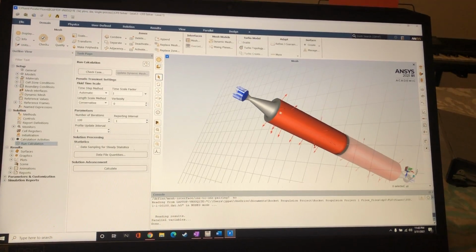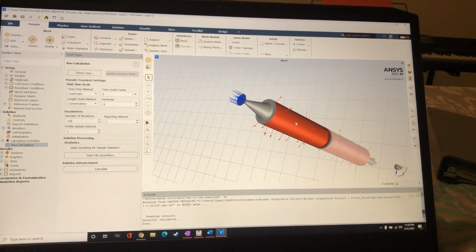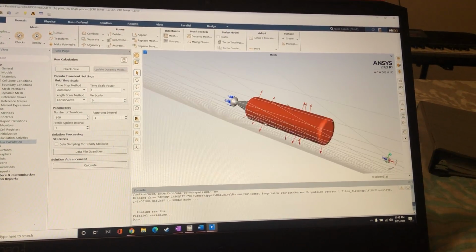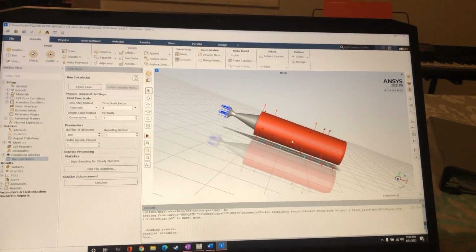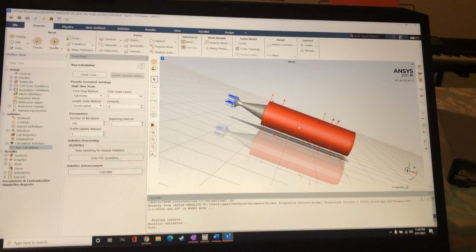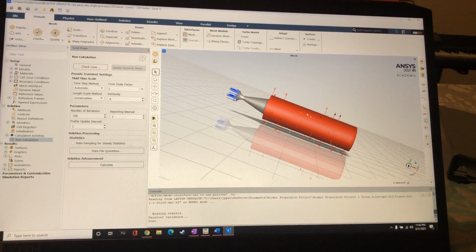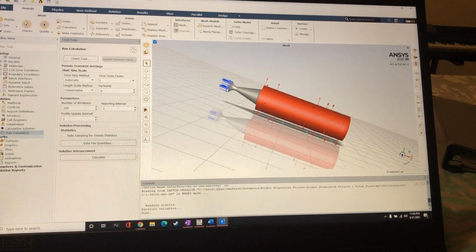These 3 faces had to be approximated as walls because I did not want any fluid flow out of the nozzle to turn back on itself and go backwards. And then I called it the flame plume, this step here. It basically acted as an outlet where I could analyze the parameters that you asked for after they flowed out of the nozzle.